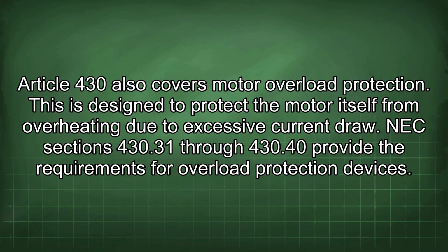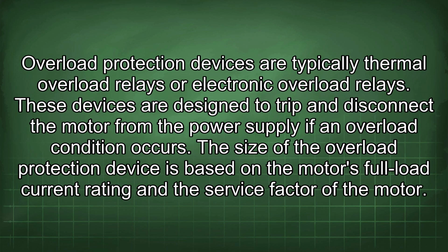NEC sections 430.31 through 430.40 provide the requirements for overload protection devices. Overload protection devices are typically thermal overload relays or electronic overload relays.